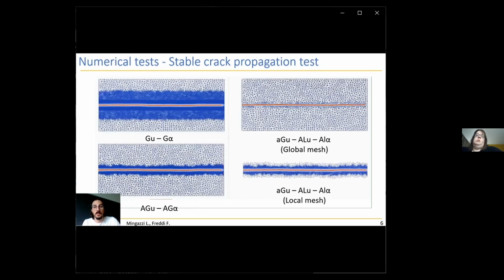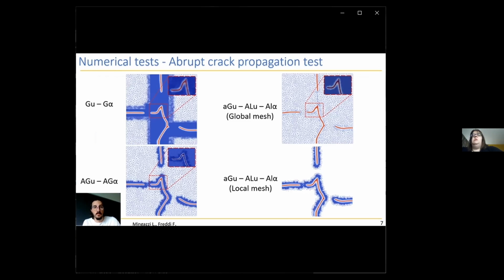The video reports the adaptive refinement evolution of the mesh for both the global and global local strategies, and it can be seen how the obtained crack pattern and width of the damage transition zone coincide with the results obtained from the standard phase field solution.